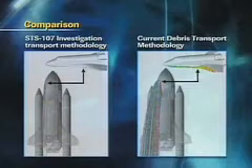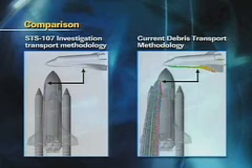And on the right-hand side of that slide, it shows what our current debris methodology does. And what you can see is instead of a few number of traces, we have a large number of particle traces. And instead of covering a small part of the orbiter structure, it covers a much larger part of the orbiter structure. And the color is basically proportional to the velocity of impact. And what you see is that we have lower velocity impacts up front and much higher velocity impacts as you move back towards the aft of the vehicle. And so that really did a lot to improve our understanding of the problem from mathematical cases.